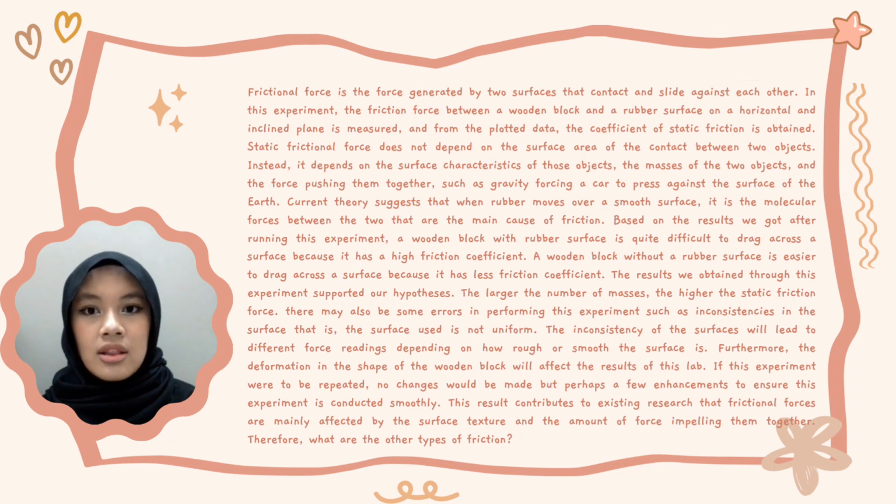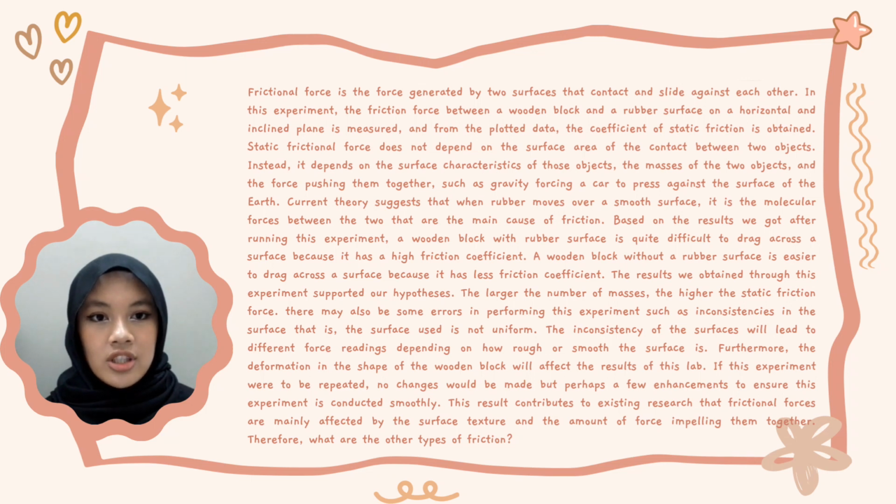In this experiment, the friction force between a wooden block and a rubber surface on a horizontal and inclined plane is measured. And from the plotted data, the coefficient of static friction is obtained. Static frictional force does not depend on the surface area of contact between two objects. Instead, it depends on the surface characteristics of those objects, the masses of the two objects, and the force pushing them together, such as gravity forcing a car to press against the surface of the Earth.